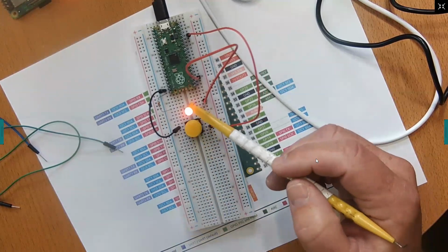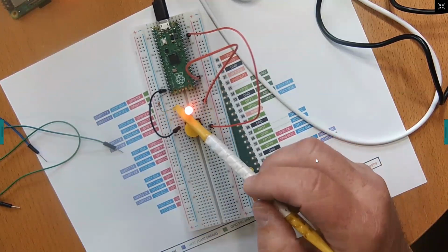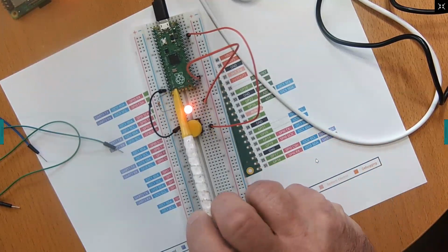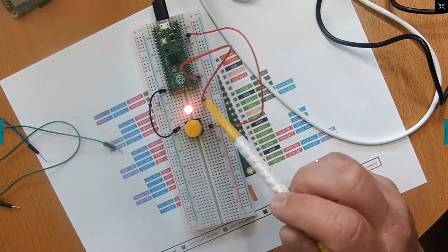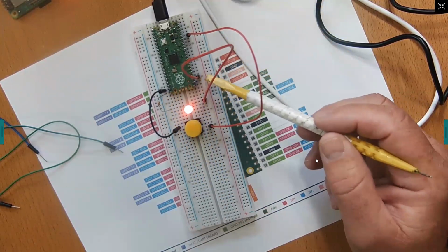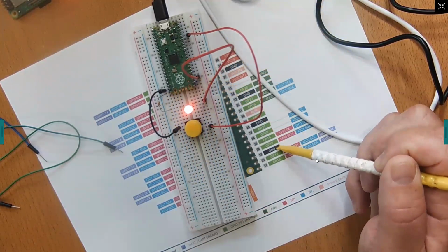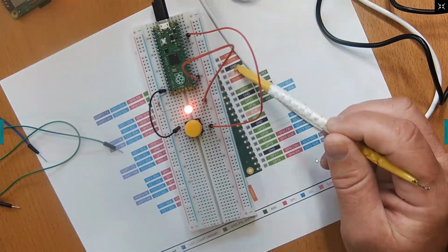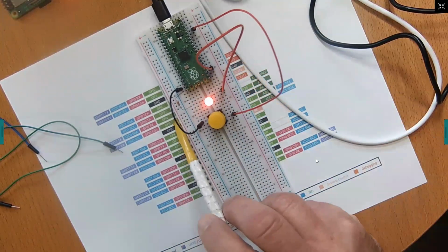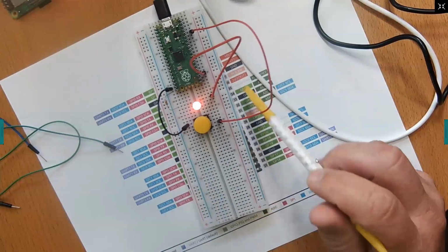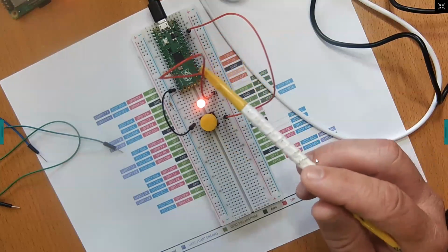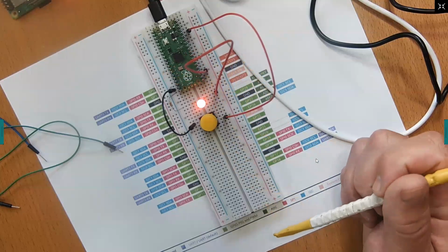So I left the wiring for the LED in place. The wiring through the resistor is connected to pin 15, that very first pin there. And this red wire here, I moved it to a ground, just to show that I put it on this ground down here. You can leave it on this ground up here if you want. You could put it here, you could put it there. Looks like there's 1, 2, 3, 4, 5, 6, 7, 8. There's 8 places where you could plug in the ground wire. That's this wire here.